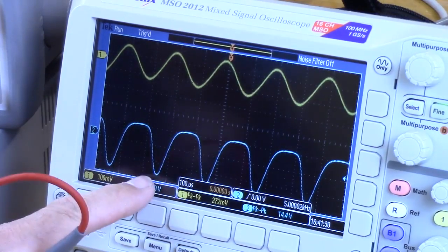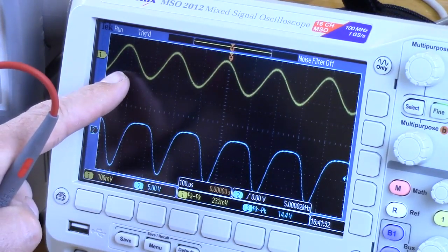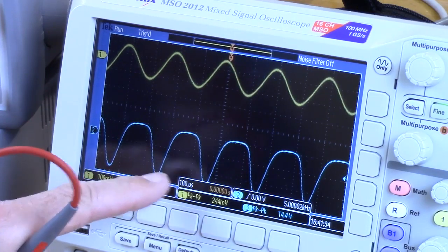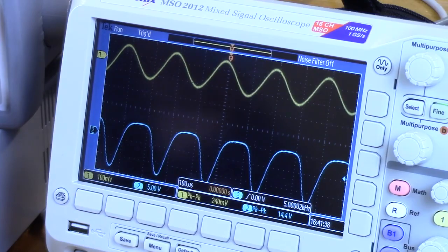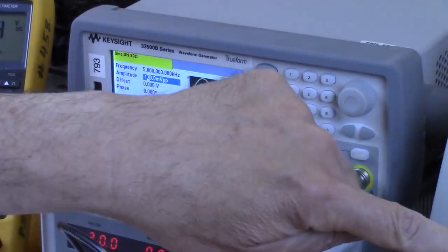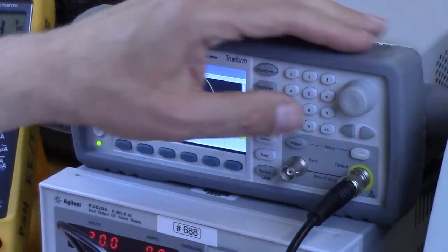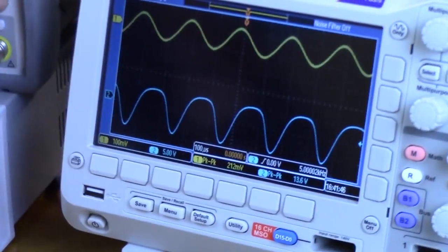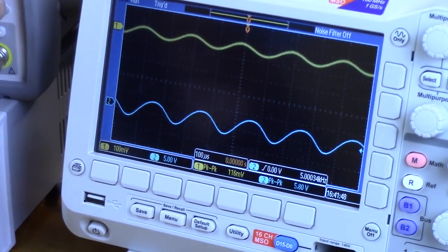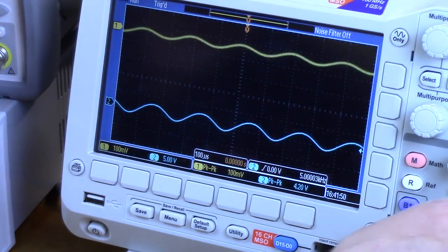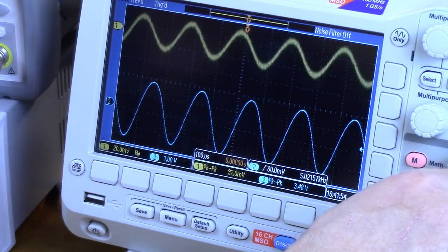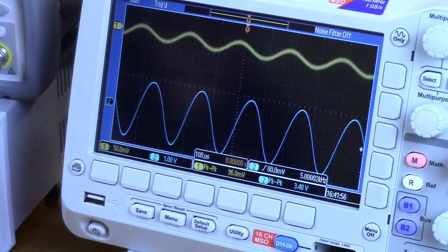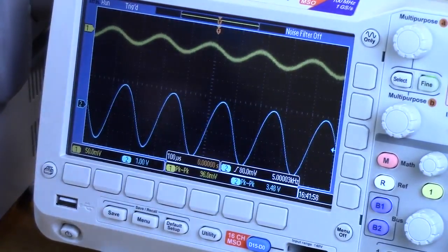This is 5 volts per division. This is 1/10 of a volt per division. And we're overdriving it. So what I'd like to do is cut the input signal down in amplitude, parameter, amplitude, to make it so that the output here is coming through undistorted, even if it's not making a full blast output. That's okay. So now we've turned the input way down, but we've got a nice undistorted output. And this is a waveform we can trust to take measurements.